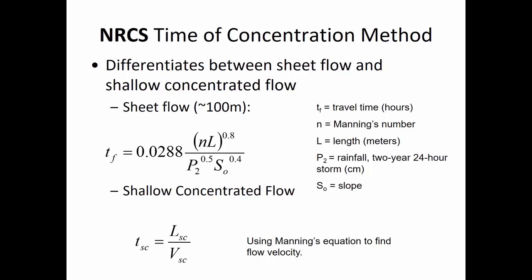You can also physically measure, like in a parking lot, if you pour a dye, like a visible dye, like some red food coloring. You yell to your friend, okay, release the food coloring, and then you're standing at the drain. And when you can see that dye, like when it's visible, or there are ultraviolet dyes that you can use, with equipment that would sense it, so people aren't being disturbed by blood running through the streets or whatever. And so you're physically looking for some sort of a tracer, as it's called. So those would be two ways of physically measuring it.